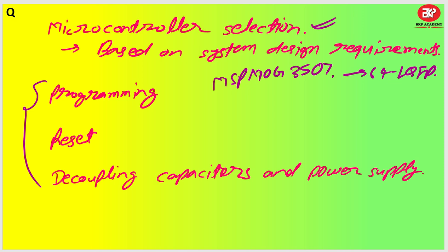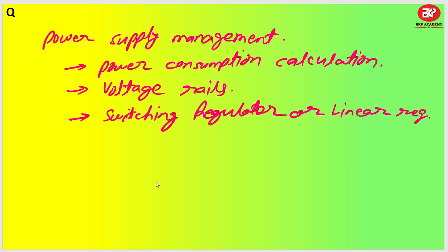So the next question is, no design is complete without a power supply requirement, right? Any design will need a power supply. So for that you first have to calculate the power supply consumption, whether 200 milliampere or 100 milliampere is needed as total consumption of the system. There are a lot of other discrete circuits, your microcontroller and other things, so you have to calculate how much consumption there is one by one, let's say in an Excel sheet, or maybe there are some tools through which you can calculate them.